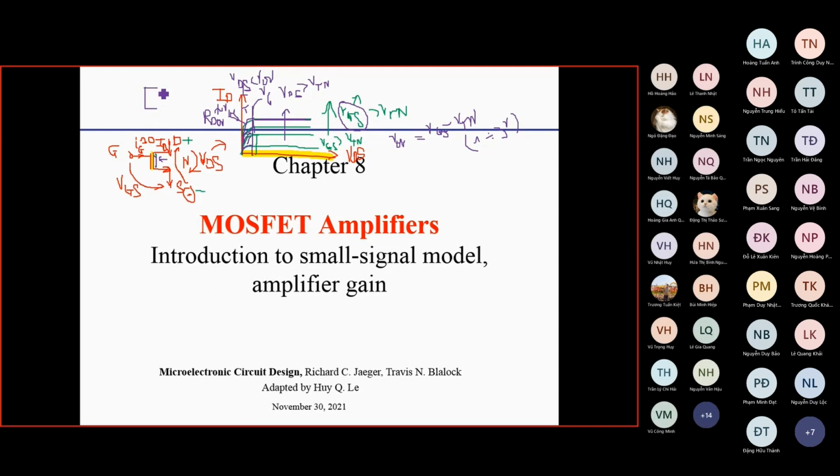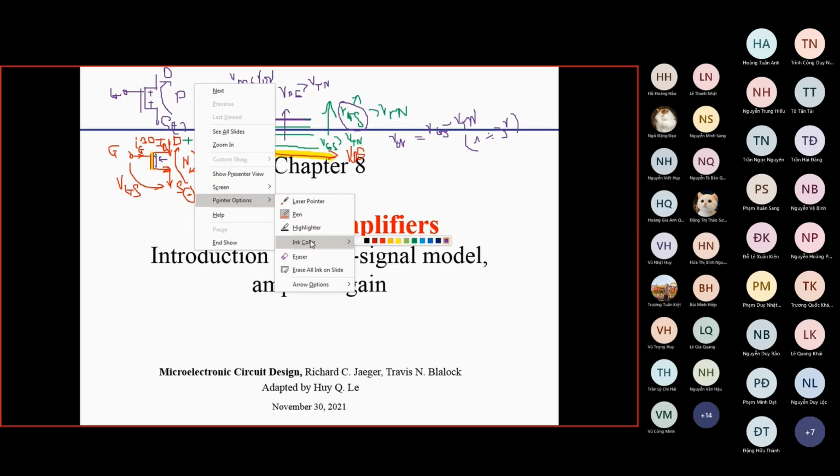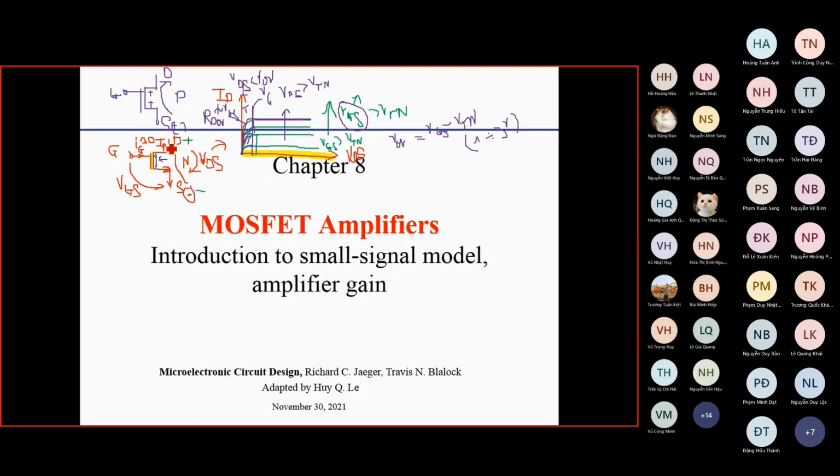It goes similarly for the p-channel field effect transistor. Okay, so on the gate here for the p-channel, the carrier is positive, so holes start from the source and run to the drain. If the positive carriers run from the source to the drain, that means the current also runs from the source to the drain. So the arrow is in the opposite direction.